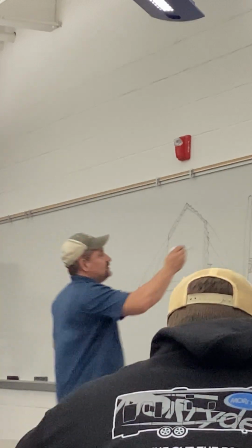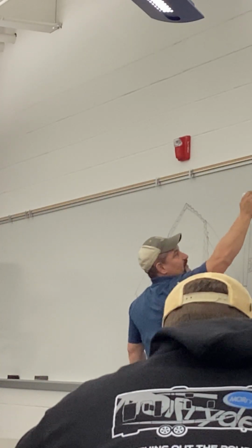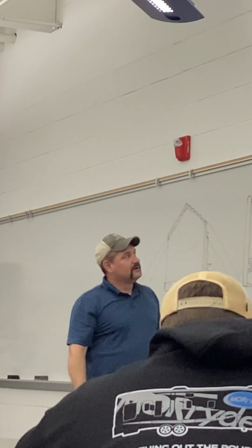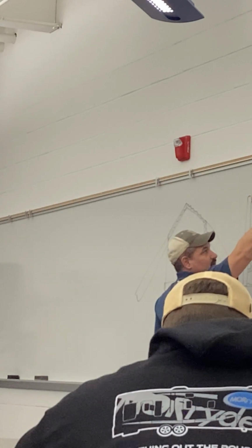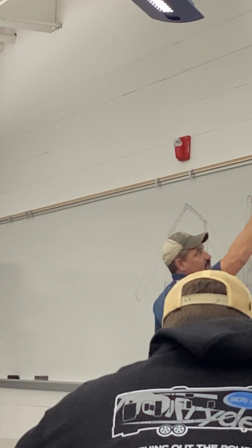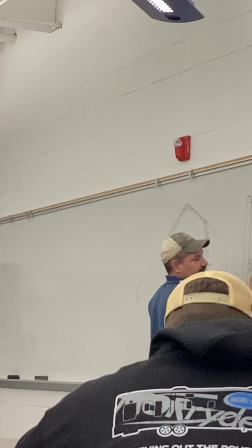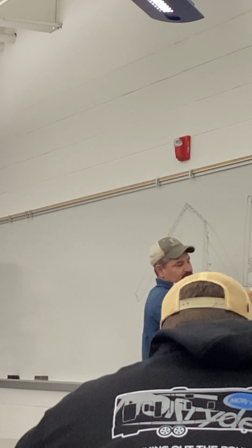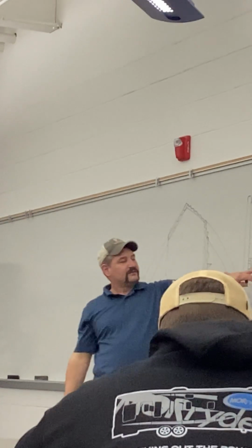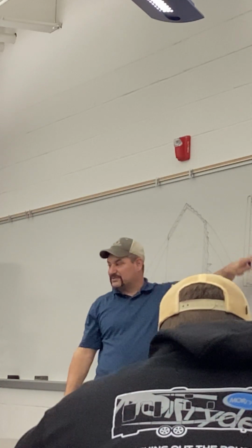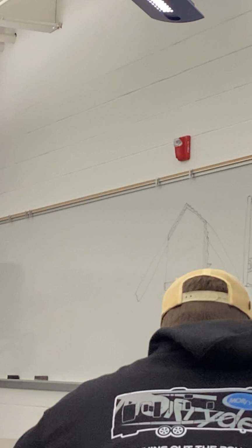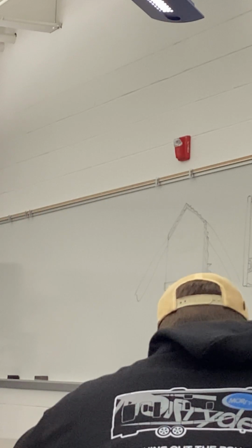A gap, you can't really see it, but if it doesn't go all the way to the top and it doesn't go all the way to the bottom, and you got gaps everywhere, a good person is going to make sure it's totally filled. There's no holes. The outlet is not only cut around, but stuff is stuck behind it, and it's all the way to the bottom. This insulation is 40 to 60% better than that, and that's just a little bit of time. Okay? So, when you're looking at all this stuff, understand the application.